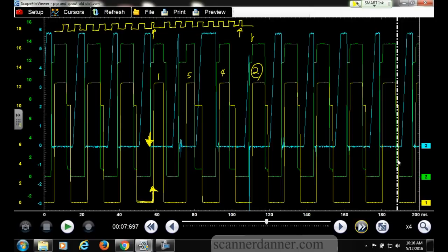That was the one why I made you guys switch the plug wires, switch the plugs, no change, a physical dropout in just the number 2 cylinder. You would swear on every single system out there that it was a cap and rotor problem. This is not a cap and rotor problem. It's cool we got a new distributor. The owner did give us a cap and rotor for this. But when we put this back together and do our after pictures, we're not putting the cap and rotor on until we're done, because I want to prove it.